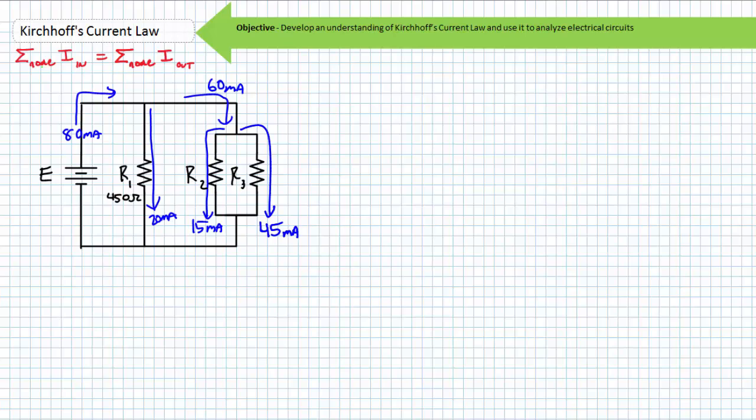There is absolutely no difference between this illustrated example problem and our previous illustrated example problem, with this one minor exception. Solve for voltage across these resistors and solve for the resistance values of the unknown resistors R2 and R3, given that R1 is known to be 450 ohms. Here's where your knowledge of basic parallel properties, Ohm's law, and spatial awareness comes into play. Voltage across elements in parallel is the same. Resistance is voltage divided by current.